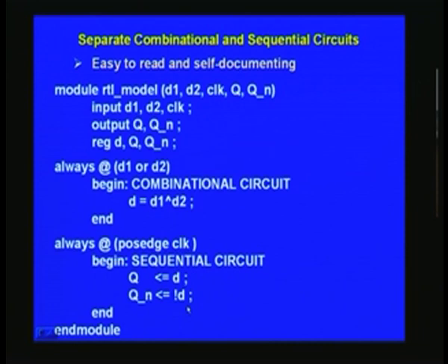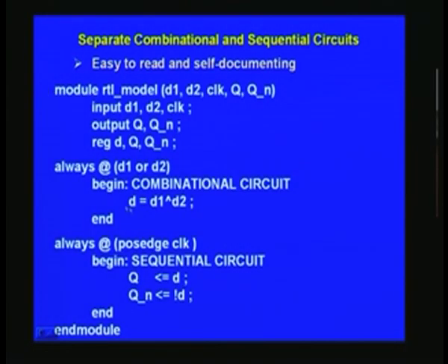A module is something like a black box. You have a block diagram with which you are already familiar. It will have IOs, and that's precisely what you have here. So that block can be given a particular name, and the block itself we call here a module. And once you have a module, you should signal to the tool that is going to process further by another corresponding signal called endmodule. And note that there is no gap between end and module. It's a single word as such. So module, endmodule. This is a vital thing that you have to keep in mind.